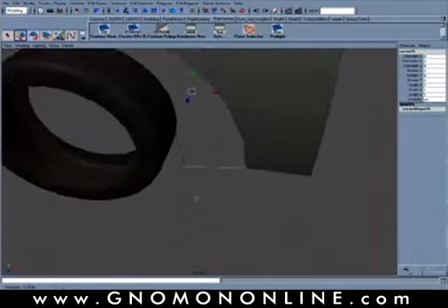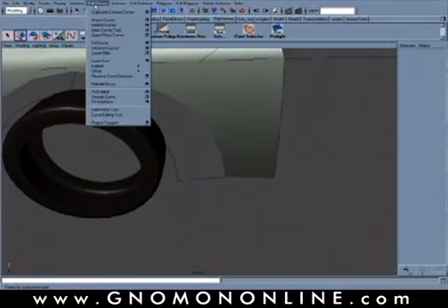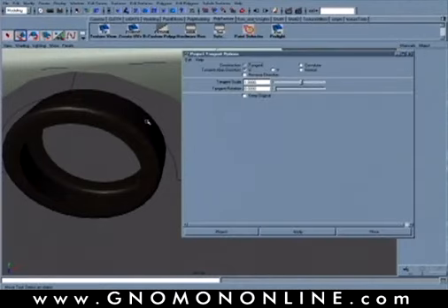And to do this, we'll use the project tangent tool. Project tangent you find under edit curves, project tangent right there at the bottom. It will have options in here for how you want the tangency created. You have the options of tangent or curvature. Right now we'll use tangency. Which direction do you want to line it to? The U or the V of your original surface, or coming normal or basically perpendicular to the surface.